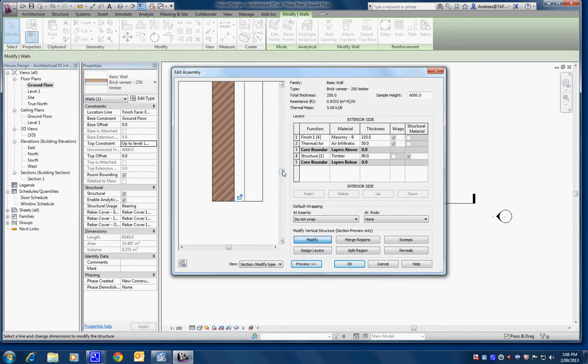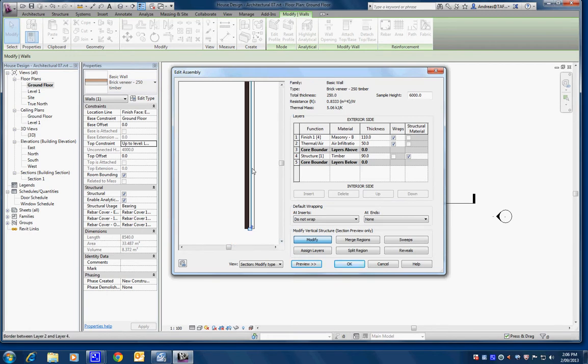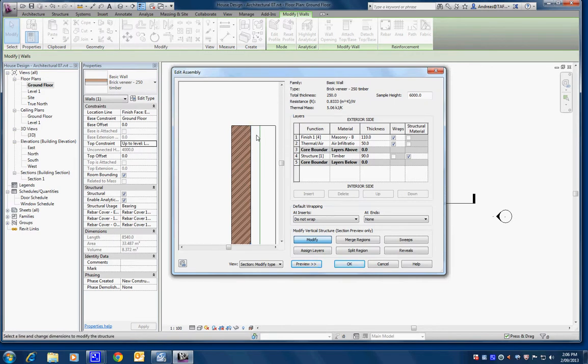Alright, so that's that. So now it's unlocked up, I'm able to modify that independently of the whole wall. I'll do the same thing at the top because I'm envisaging later on, and I'll just zoom this out, I'm going to have to drop the external leaf down because of the roof slope. So these will not end up being the same height. So I want to have that flexibility ready for me. So I'll unlock the cavity as well, and we'll go OK.